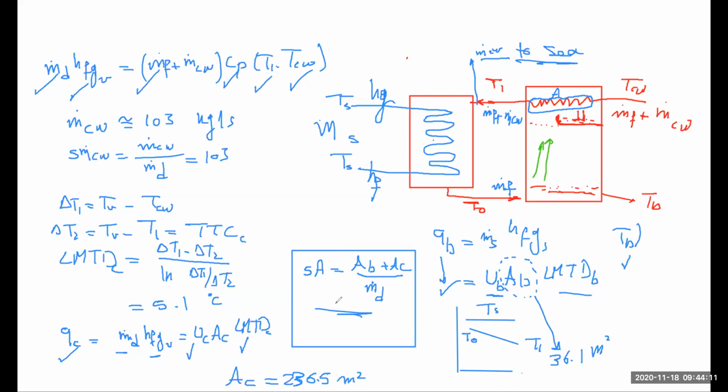So now this is the kind of analysis which is normally done with a single stage flash system. We started the problem not knowing a couple of temperatures that we could obtain from that temperature profile by just plotting the temperature profile. And that's why I want you to be able to draw it on your own. And then we did not have the rejected brine salinity. We did not have the feed flow rate. So we have to make an energy balance for the stage so that the kind of vapor that has formed here is formed due to flashing.